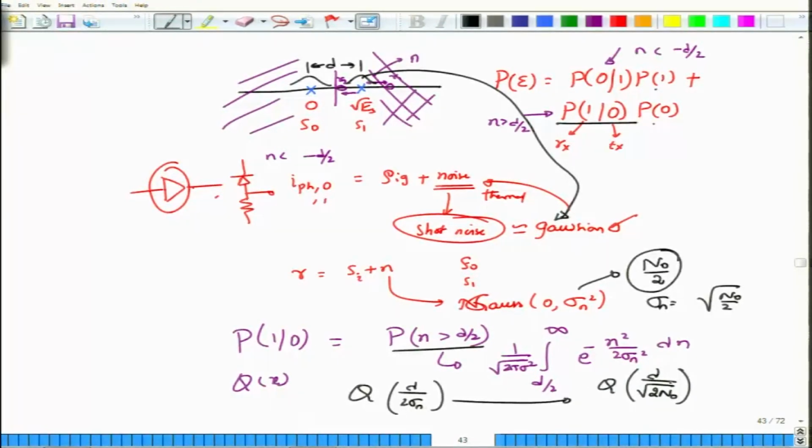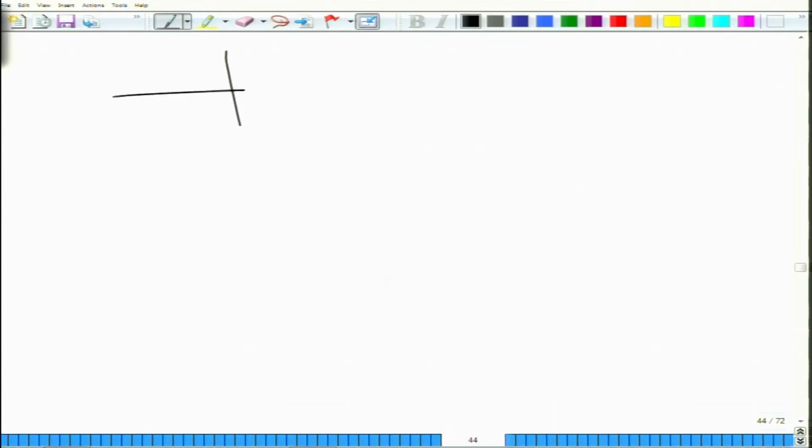So, this is the probability, multiplied by half, plus the same quantity again, and therefore, this is the probability of error for this system in which the two symbols are separated by a distance d. Please note that the only assumption that we have made is that of the Gaussian noise distribution and having same variance whether you transmit bit 0 or bit 1 or symbol S0 or S1. Now, it becomes easier for us to evaluate the on off keying as well as the BPSK system. So, in the on off keying, what I have here will be symbol S0 and symbol S1.